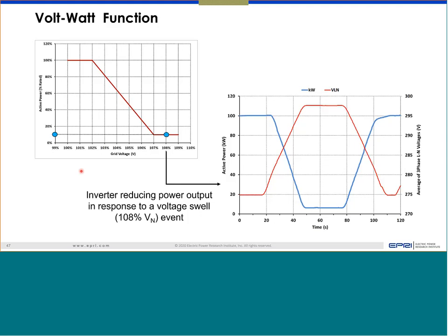There is a question: does phase imbalance affect this? That's a very good question, and we are actually investigating how inverters respond to unbalanced conditions. So far, we tested one or two inverters, and it looks like most of those inverters only respond to the positive sequence voltage, so they respond to the average voltage. They inject almost the same VAR in all three phases, responding to the positive sequence component only.